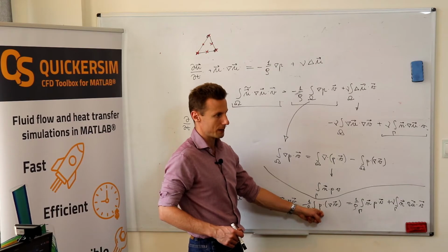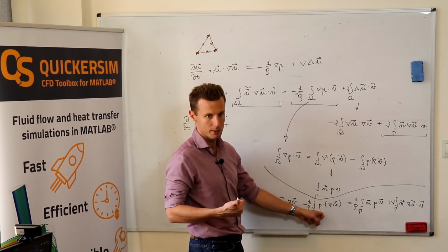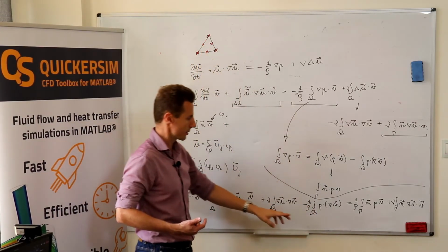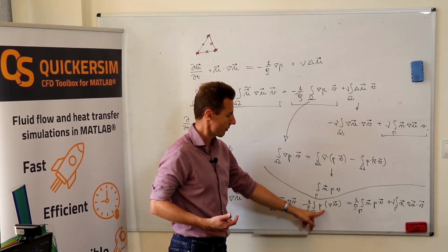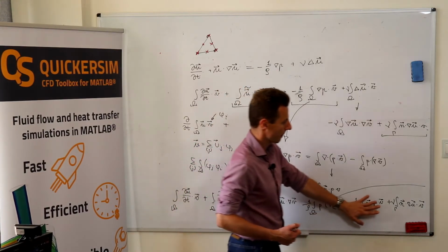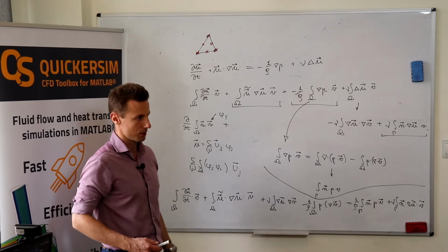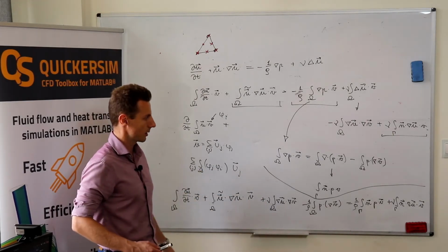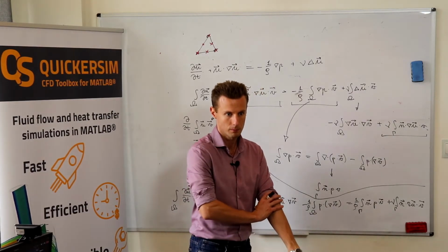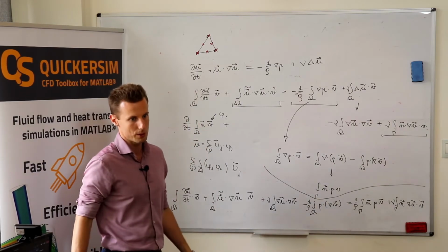This one will be replaced by the nodal pressure values times the linear shape functions for the pressure. And this one will implement the outflow boundary condition. I will go into that in a minute. Some question? I guess it's always implicit? It's always implicit.